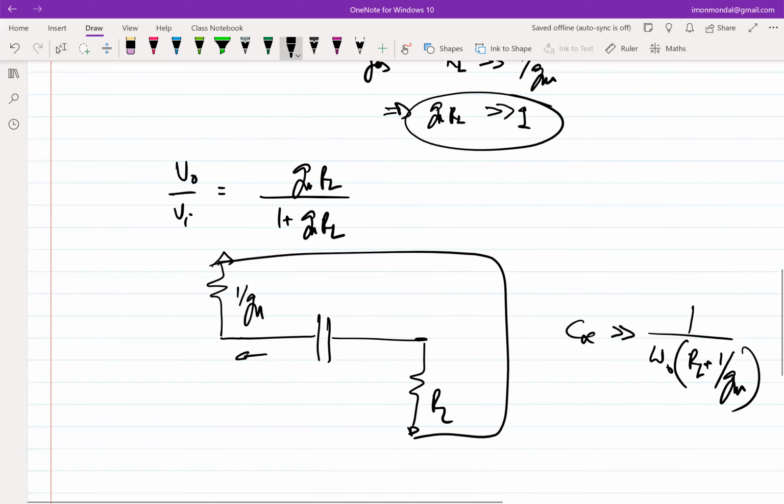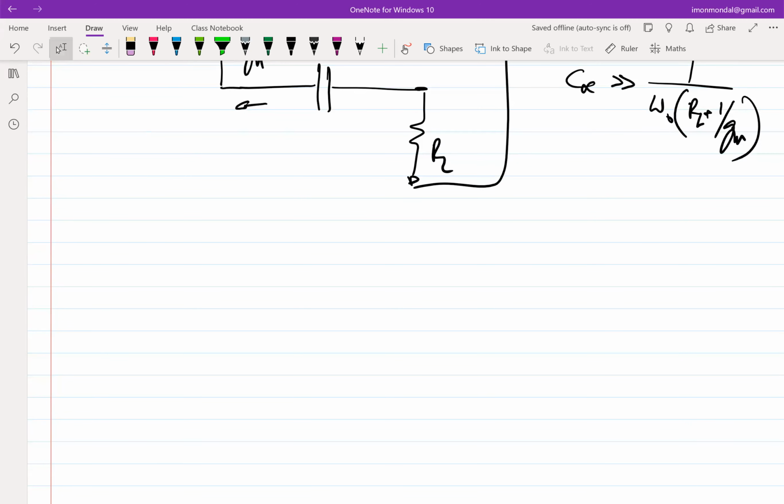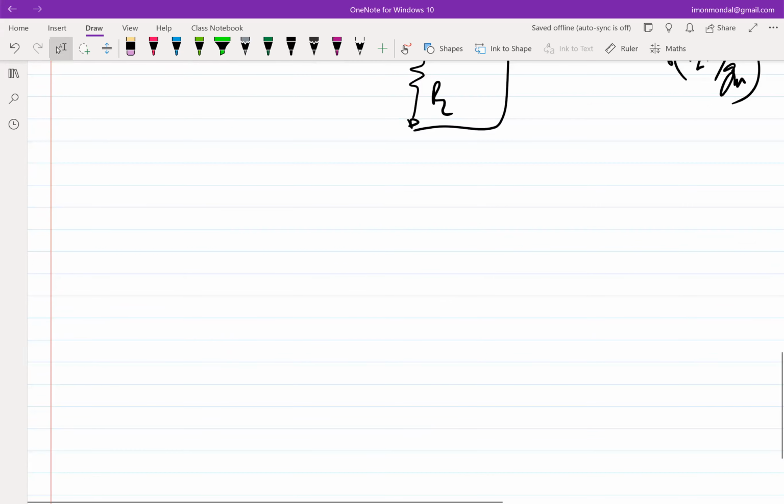Okay, so now let's move on. All these things we were doing because we wanted an amplifier in negative feedback. We wanted the amplifier in negative feedback to have a stable GM, because all the parameters were strong functions of GM, especially unity gain frequency, phase margin, DC gain, everything. So we wanted an amplifier whose incremental characteristics are independent of ambient variation, like threshold voltage variation, and less dependent on the mobility variation. That's why we were looking for architectures which can be biased using a constant current source, because we saw that constant current source biases have these good properties.